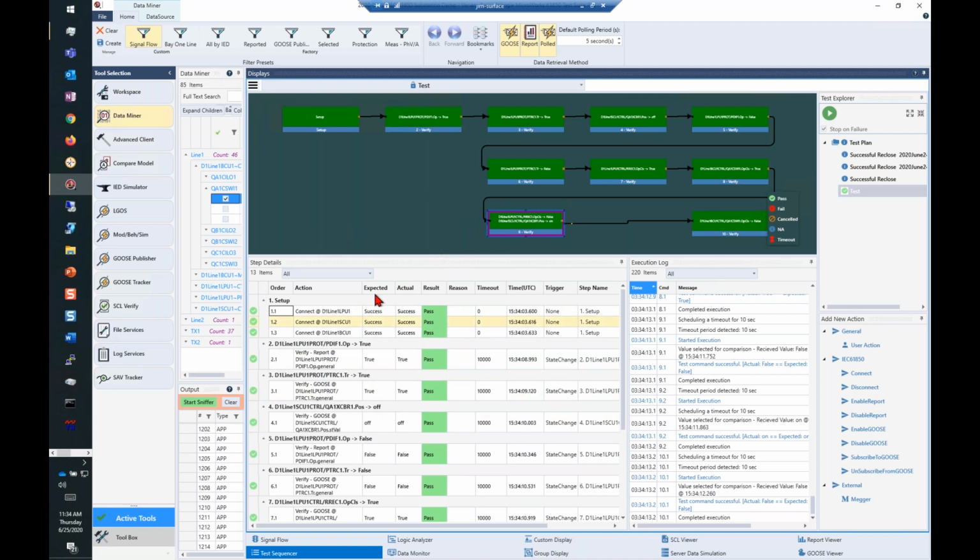And that's what the value of these regression tests is, when you're integrating new equipment in, working with DTM, you disable that device in DTM, put the real equipment on the line, and then it can interact with all the equipment and see if you can pass all these regression tests again.